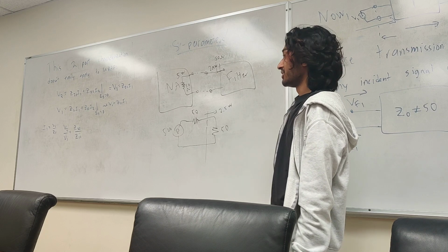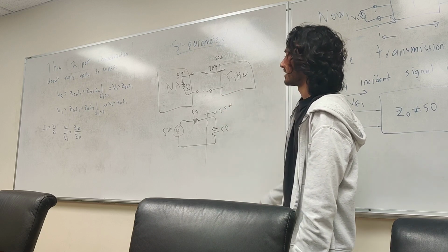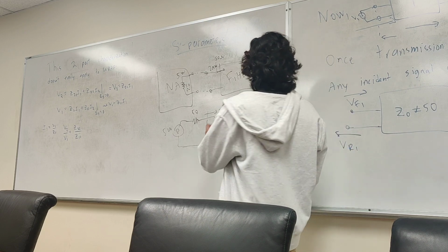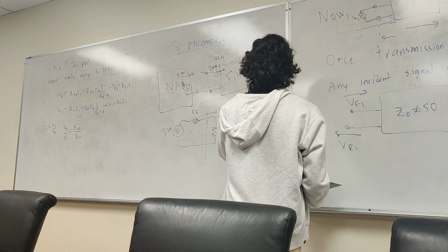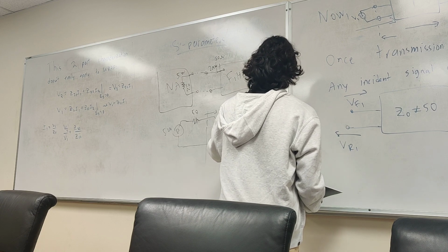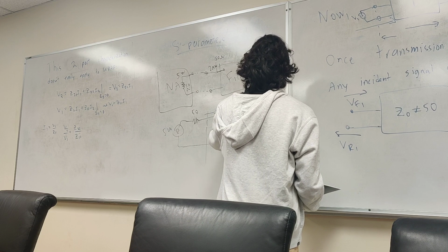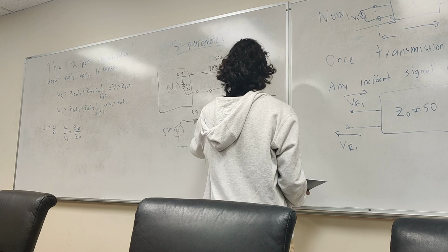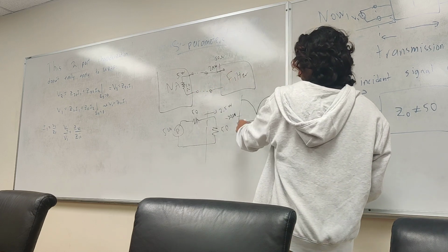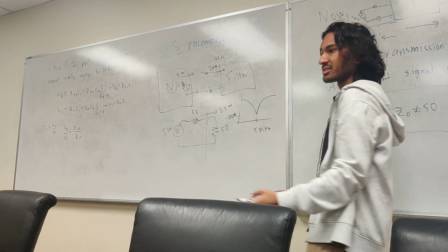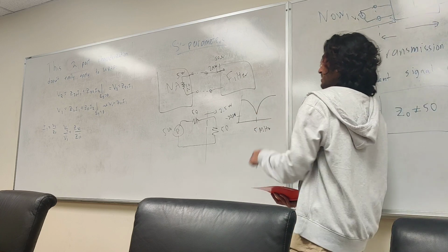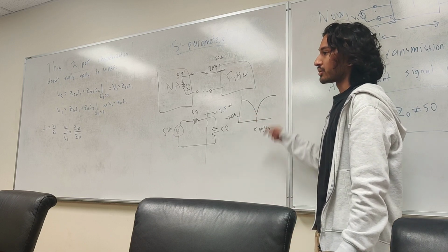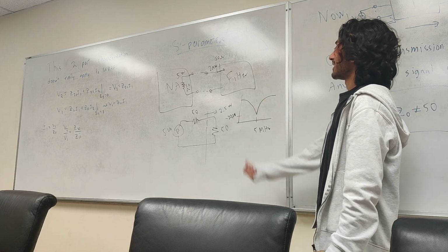That way, when we use our Nano VNA for the filter, and we look at our S11 and our S22, we can say, hey, if it's matched, we expect, I can draw out the curve here. So we have a 5 megahertz filter. We expect our S11 to be something like this, our bandpass. Let's just say this is negative 20 dB, right? Nano VNA is dB, so this is a power quantity. dB for S parameters means power. Negative 20 dB means that pretty much no power is being reflected back. One hundredth of our power is being reflected back, right? 99% of it goes through.